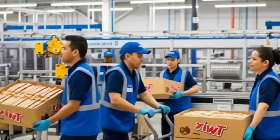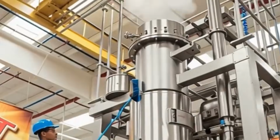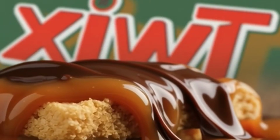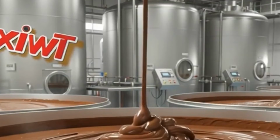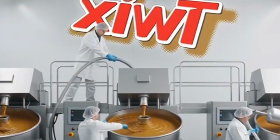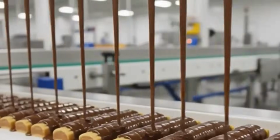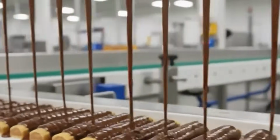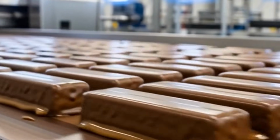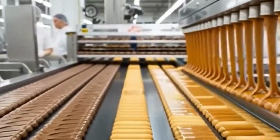Upon exit, bars pass through a vision inspection system. High-resolution cameras capture top, side, and bottom views. Pattern recognition software detects coating voids, caramel leaks, surface cracks, and dimensional anomalies. Bars not conforming to target specifications are removed via pneumatically controlled ejectors and collected in reject bins for offline evaluation. Compliant bars are transferred to the primary packaging line.